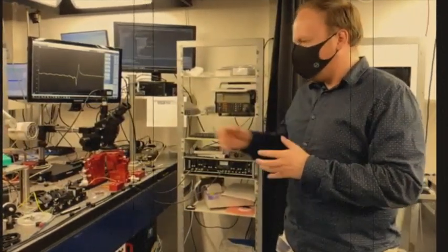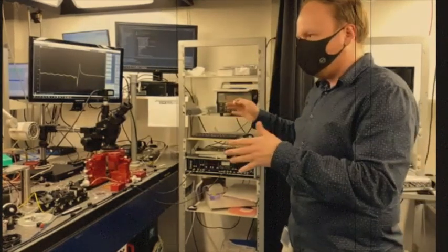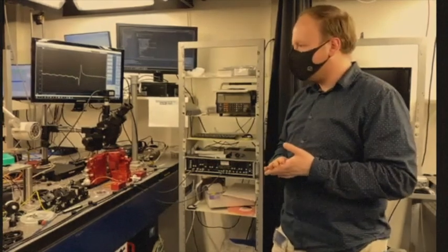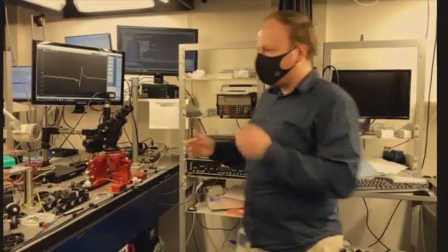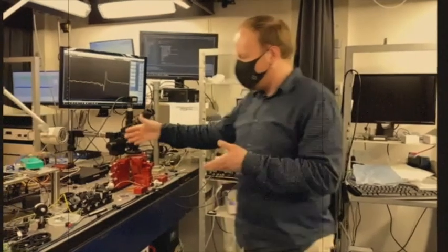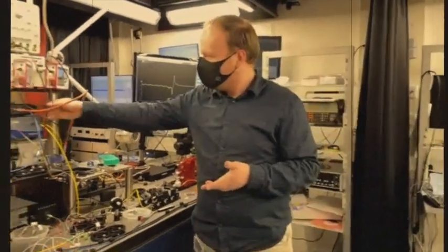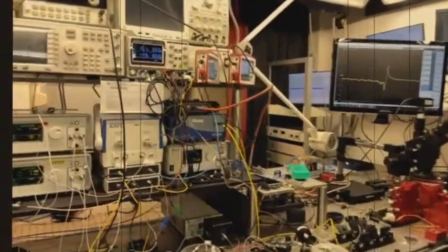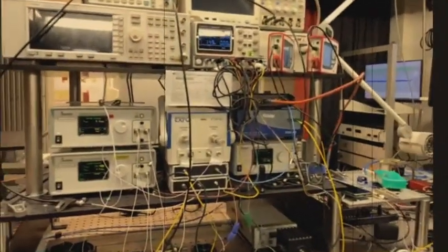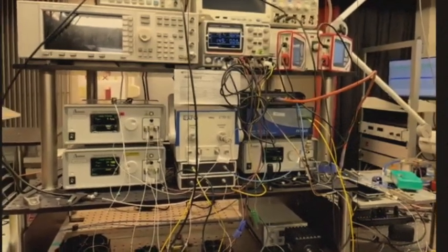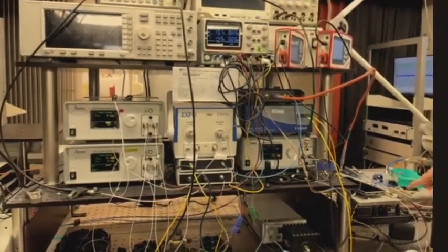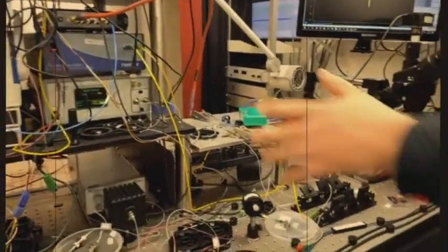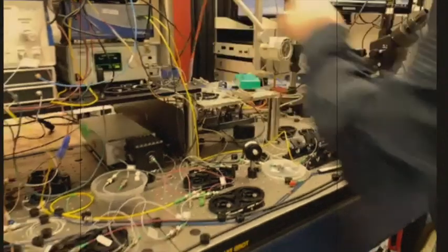In this case, we're also using a lot of RF. As far as I understand, you have electrical engineering backgrounds, so we are using RF-like techniques. We're using this vector network analyzer, which allows us to measure the transmission of an RF signal, which we then modulate onto the light and finally retrieve again after passing through everything here using a photodiode.